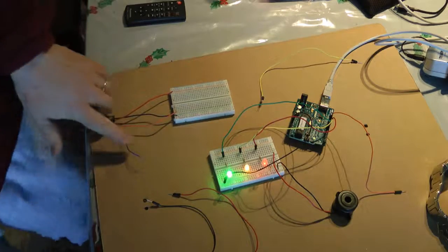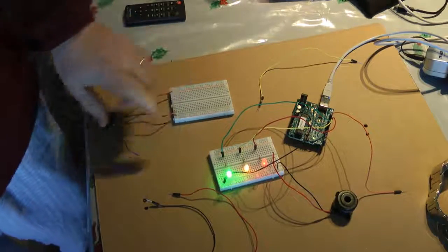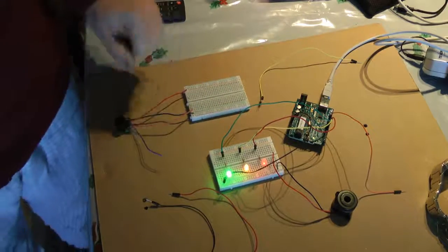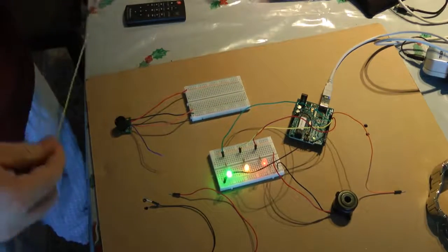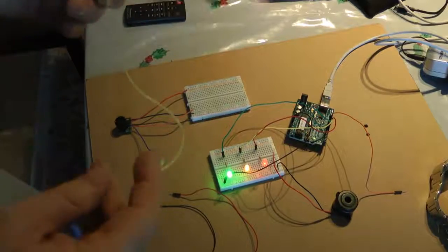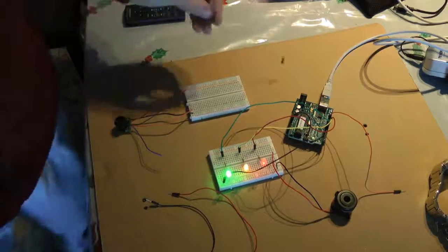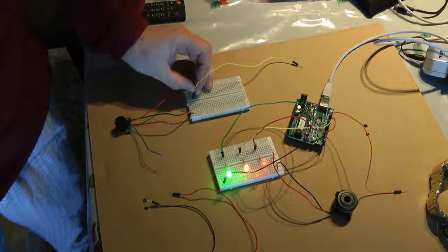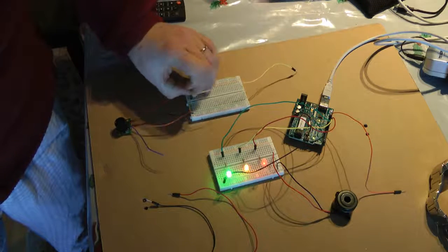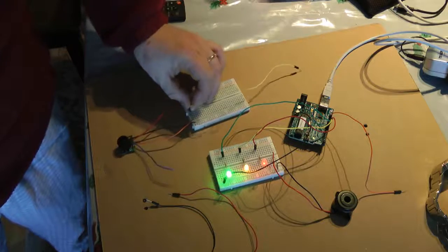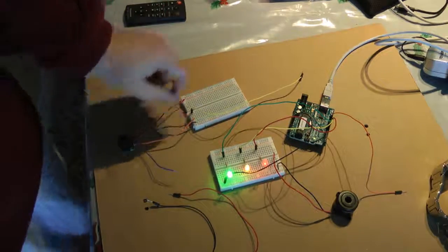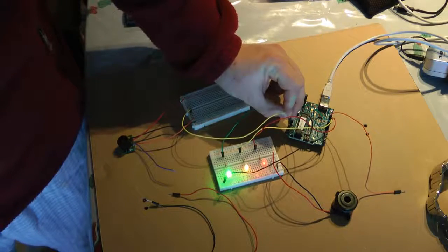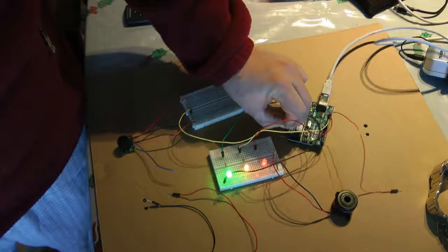And I'm just going to move this RX out of the way. The only thing we use this RX for is to shut down the sensing. Okay, so he's in there. First thing I'm going to do is take the sensor, which is the analog, and I'm going to use this yellow cable for it. I'm going to put it in row 1, column E, which is attached to the same row that this is in. And I'm going to put it in analog pin 5.